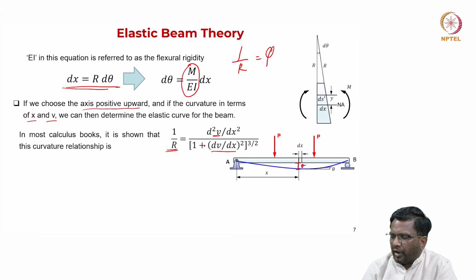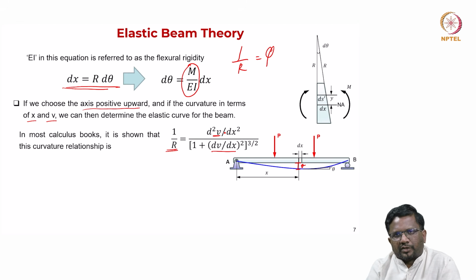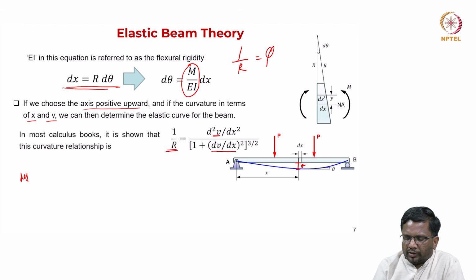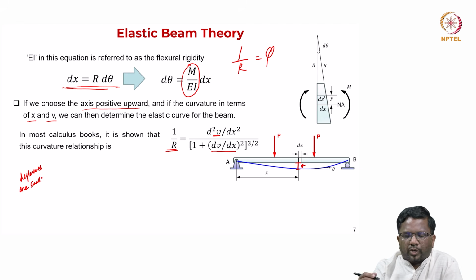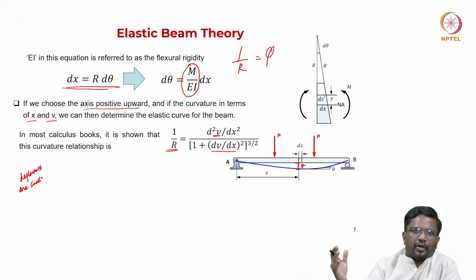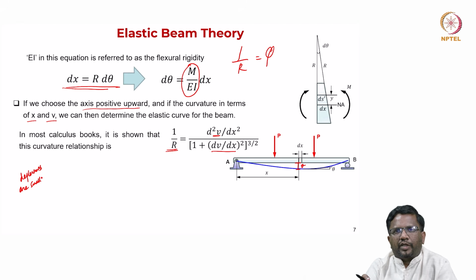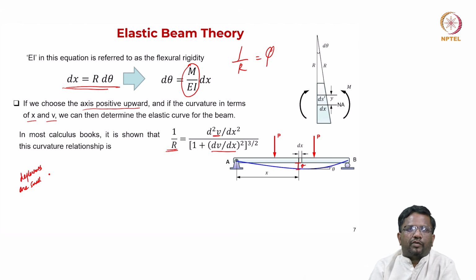So, you will have both of these, but in reality, concrete beams, or as a matter of fact any structural member, the deflections are considered to be small. Okay, what is the meaning of how small is small? Typically we don't subject the beams to more than 30 or 40 millimeters in the usual practical regime, right? Compared to the length of the member, the deflections they are assumed to undergo are going to be very small. So, we call this small deflection theory.